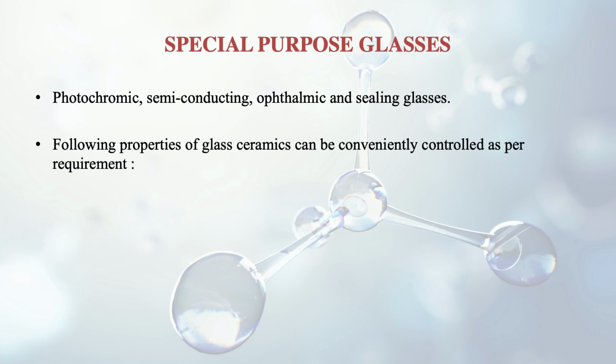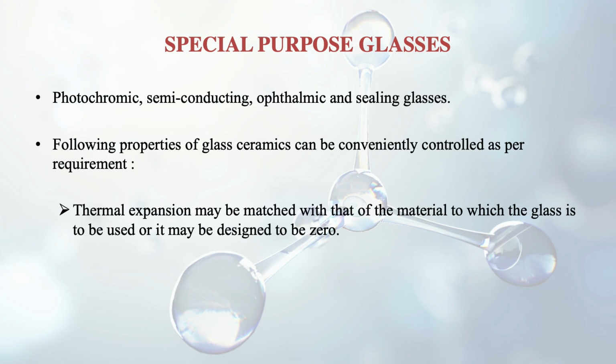First of all is the property of thermal expansion, which may be matched with that of the material with which the glass is to be used. And why does it have to be done? So that no residual stress comes in. So both this glass and the other material that is being used will have matched thermal expansions.